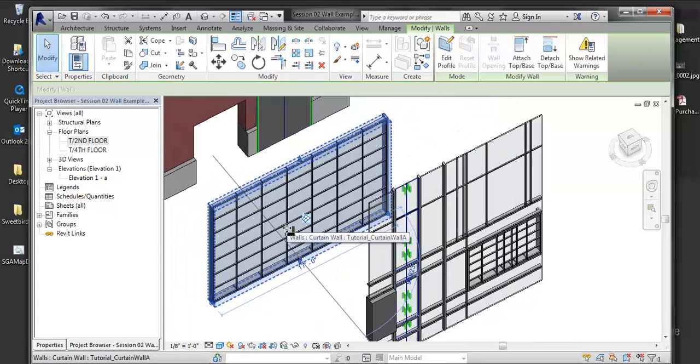When we get into scheduling, it can be an issue. But in terms of design sense, it's easier to manage patterning with it this way and treating things as panels. So I'm taking out gridding and everything else. So I'm subdividing a surface. So I don't see it as an actual curtain wall. I see it as a surface that I can then subdivide to my heart's content. If I need to do any angular kind of divisions, then we're getting into divided surfaces with actual masses and applying panels that way. But everybody's think of a curtain wall, right, is that first one.